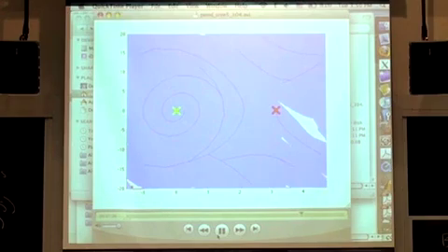So for the simple pendulum with damping and torque limits and everything set the way it was, this little randomized algorithm can sort of fill the space with basins of attraction with just a handful of trajectories. I've never said it with such dramatic force. Okay? That's the highlight of the class, right? Okay, so this is exactly the feedback motion planning idea that I'm most excited about right now, right?